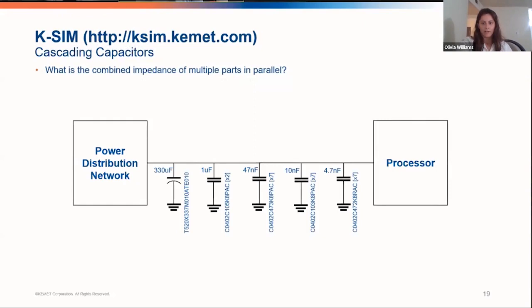So this was done, all to get the needed target impedance out of this processor over here, so that this processor can effectively and efficiently function. So real quick, we started with our higher value capacitance 330 to take care of lower frequencies, and gradually added smaller capacitance values to take care of the higher frequencies, all while trying to maintain a grip on the anti-resonant points that pop up when you have the different values put together in parallel.